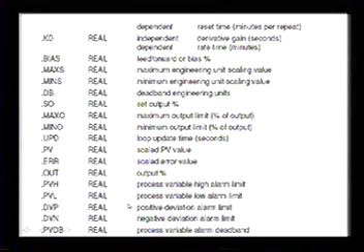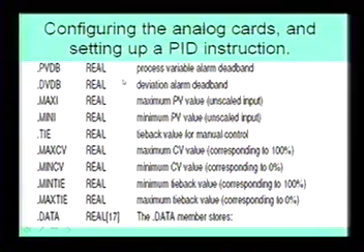And you can say, hey, wait a second, I've got a high alarm or I've got a low alarm, and you can do derivative, a deviation alarm limit, positive and negative, and a process variable alarm deadband. And here we've got PVDB, which is your process variable alarm deadband, and DVDB is your deviation alarm deadband. And then you've got your max and your min value, with your maximum process variable value, minimum process variable value,